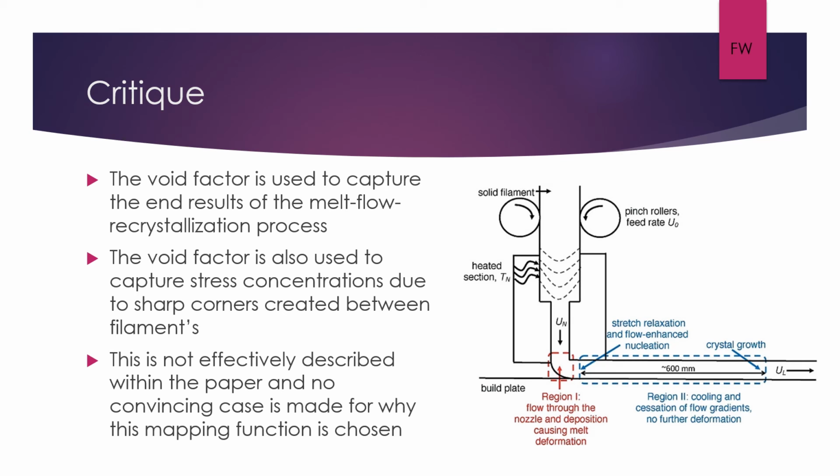One critique we have for the paper is the author's stated intent to capture the dynamic process of extrusion of a filament material inside of the void shape factor. Extrusion of the filament material involves a phase change past the glass transition temperature, involves some amount of stress and relaxation during the extruding process, and a dynamic recrystallization rate that can be a factor of different cooling effects which the printer can produce.